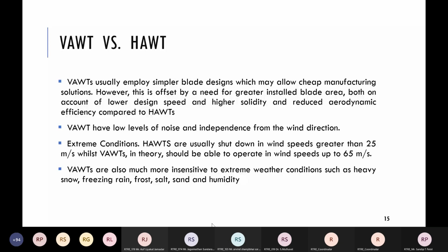That only occurs on the leading edge because the wind velocity at the leading edge will be 0. So whatever contamination or dust the air is carrying is going to sediment over there. Over time, if that sediment becomes larger, it affects the aerodynamic performance of that particular rotor.